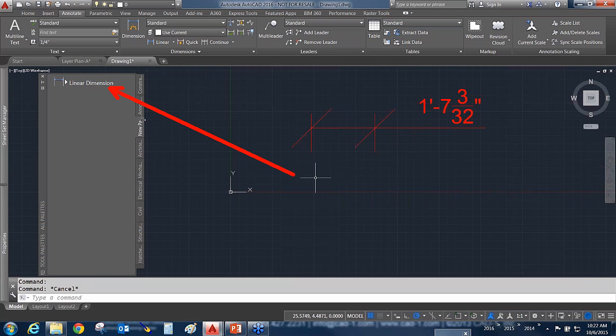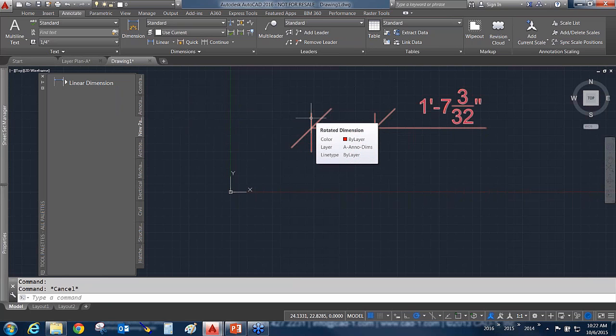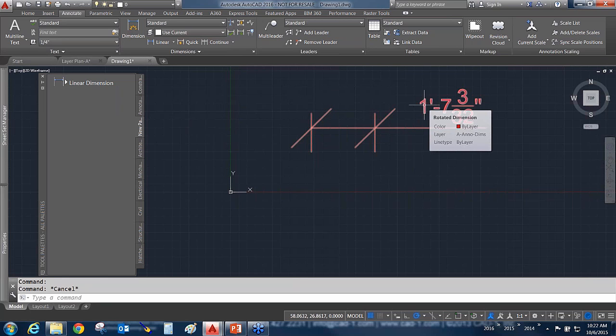Rather than do all of that, plug these things into a tool palette, so that whenever somebody wants to use this stuff, they can plug it right in by dragging and dropping content right up onto the tool palette. I'll get into a little bit of that in just a few moments as well. But you can plug all of that in there, and it maintains your styles. Text styles: what if this dimension style used a particular text style that I didn't already have? The program would build the text style. So all of that gets embedded into the tool palettes.